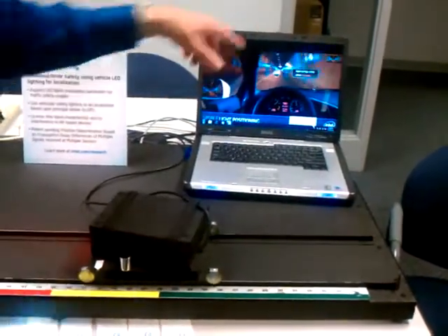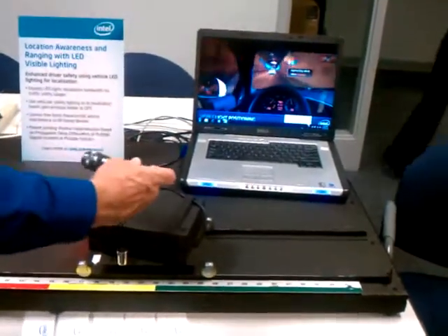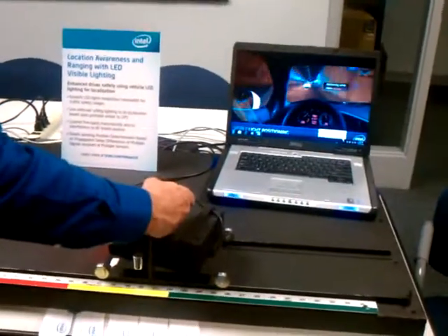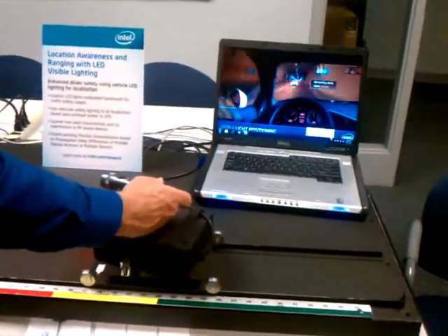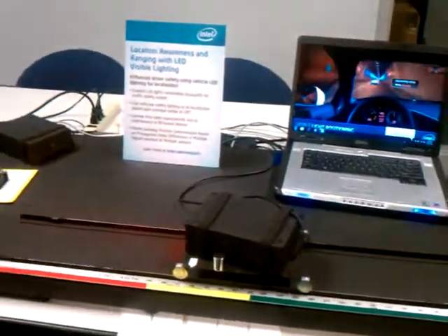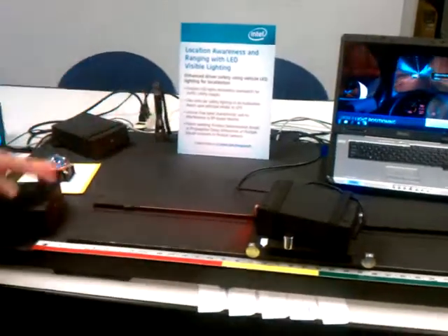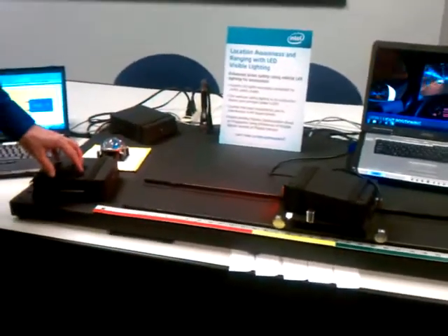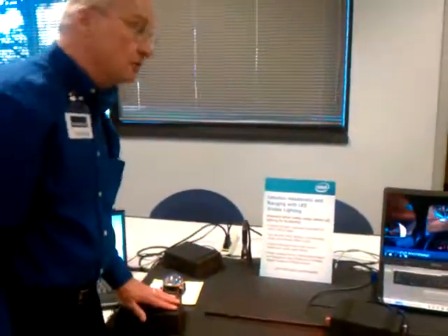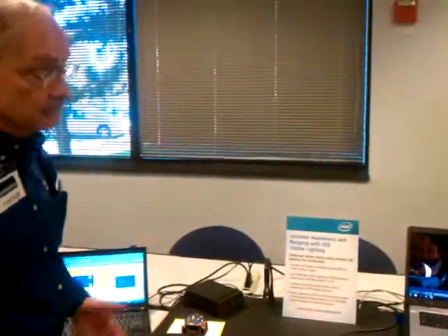Here it says 18.2, and I can shine my flashlight right into the lens, and as you can see, it has absolutely no impact. Your filters on the detector. Exactly. Filter everything out. At the output of the detectors, we have a 20 megahertz bandpass filter. As long as the detectors don't overload with the light intensity, then we stay linear, and you have a linear system.